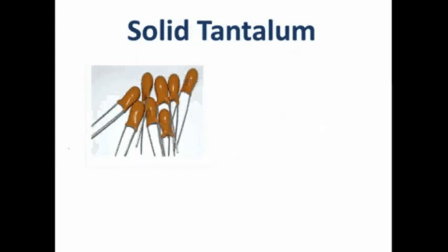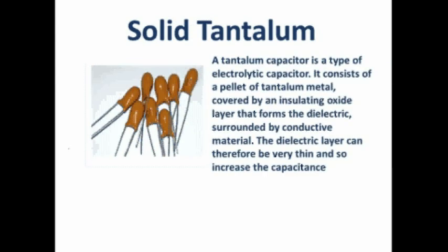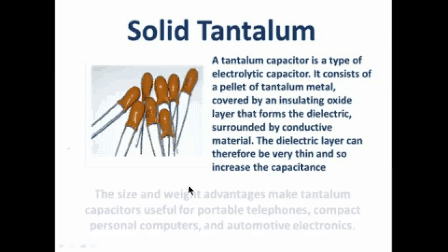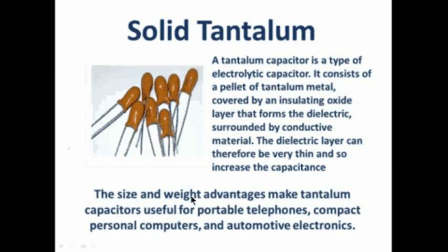The solid tantalum, now these are another form of electrolytic capacitors, and so they must be connected with the correct polarity, positive and negative. They too have a very thin layer of dielectric, and so for a very small capacitor they can give a high value of capacitance. They're used in portable phones, compact computers, and automotive electronics.